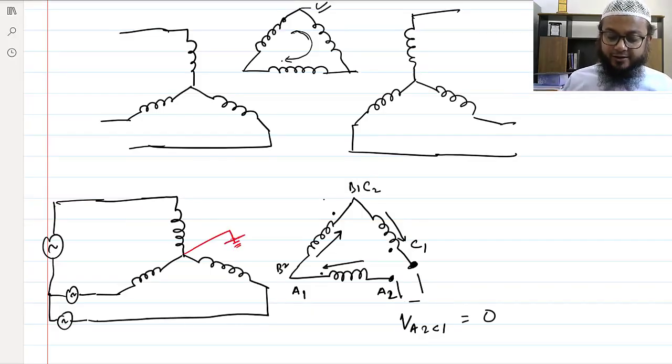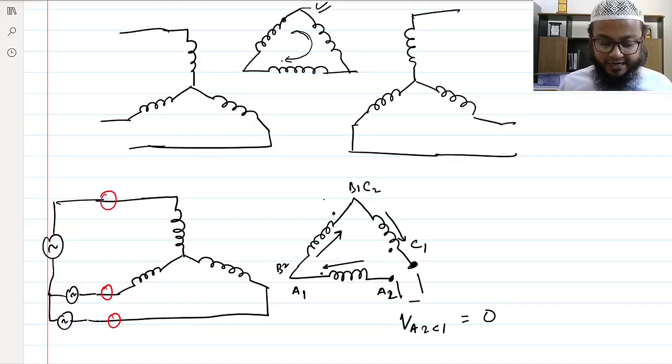Okay, and before grounding, what we did is we were observing these currents in these branches, using a current probe to sense this current. Obviously, if I'm sensing this current, the sum is 0. That means IA plus IB plus IC is actually 0, right?